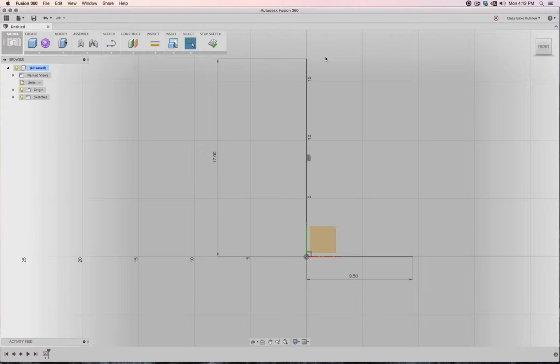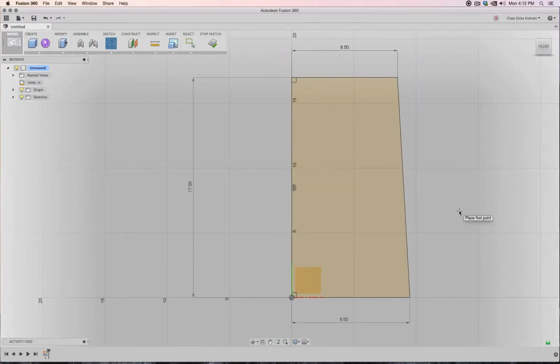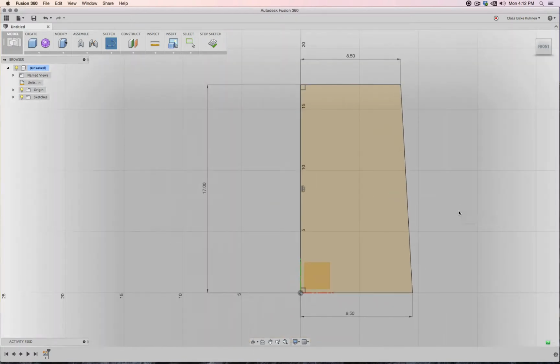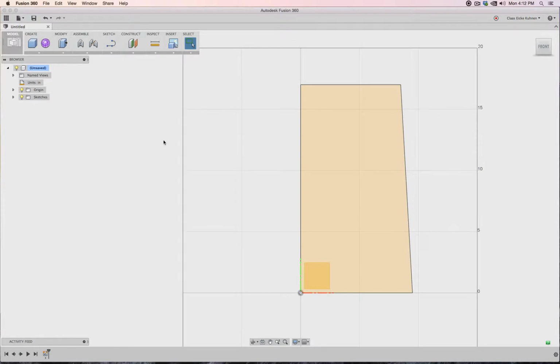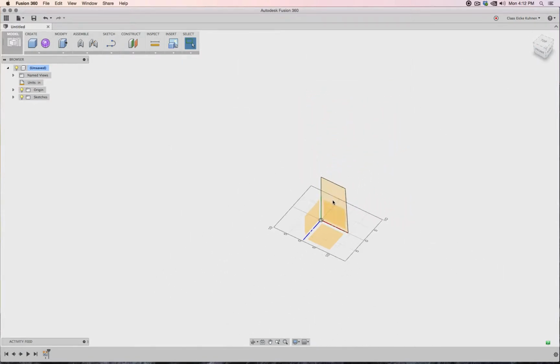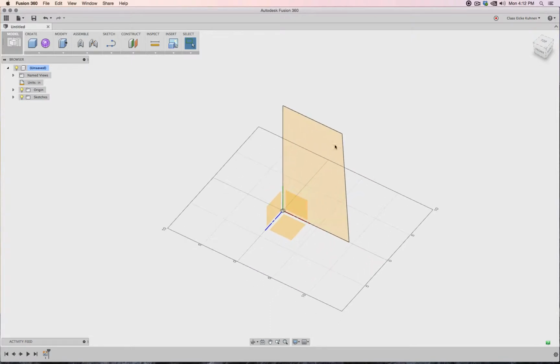Let's say the top should be 17 inches wide. So here I could go ahead and click, 17 divided by 2, press enter and click, and see if I go straight down. Go to there, I can click, and I'm good. So I can click Stop, go to my 3D view, and now there's my 3D sketch.